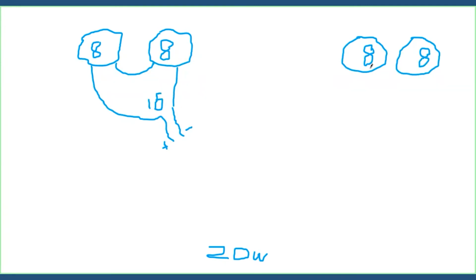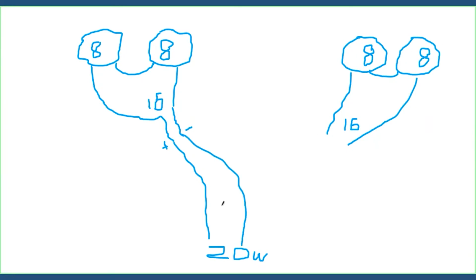So if we do the same thing over here on this side, we've got a 16 ohm load here too, right? Everybody agrees with that? Series circuits, we add everything together. But we have two same resistance values together. So now if we wire up just like that, we're moving air with two speakers, but we've just doubled our impedance load to the amplifier. What's going to happen right there?